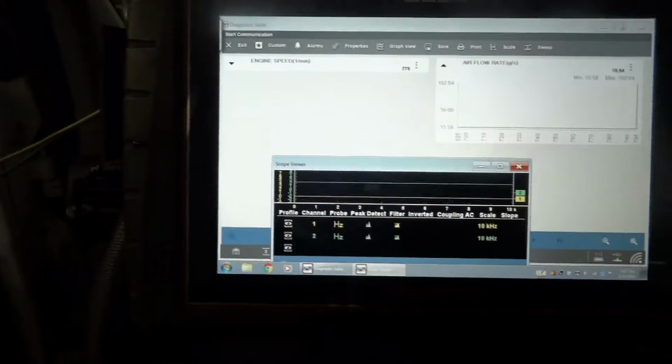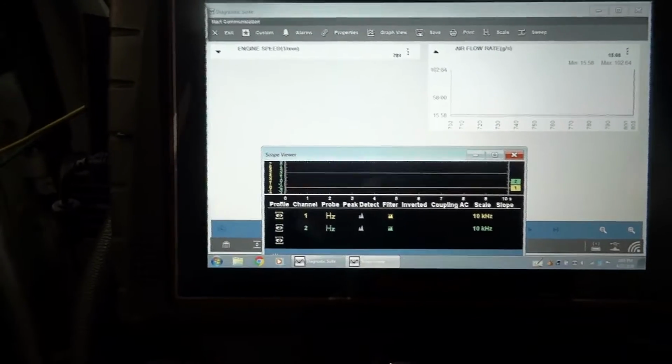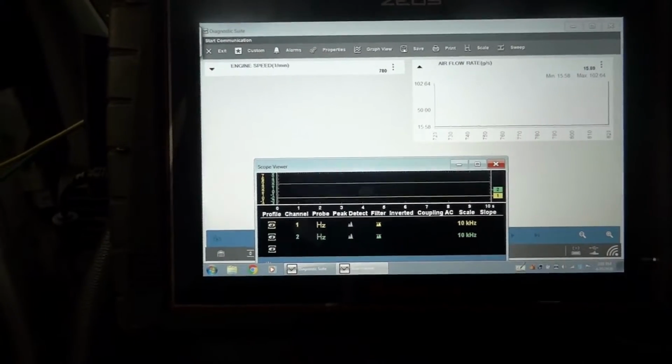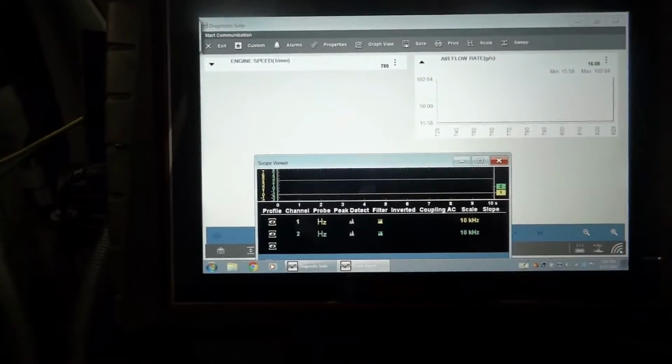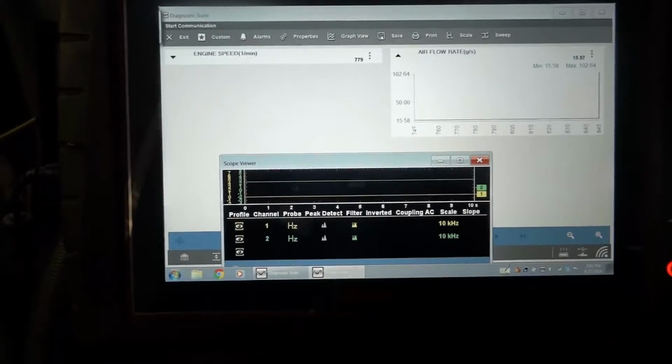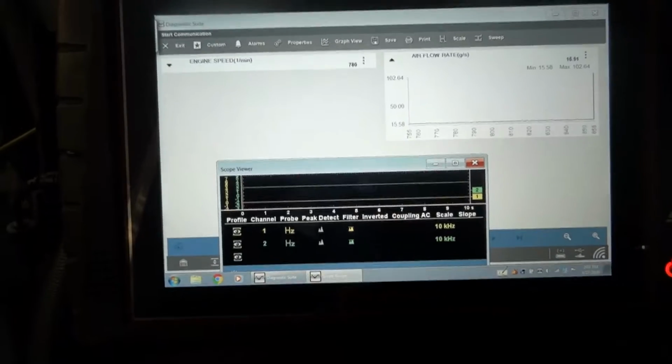I'm gonna start from the turbo, working my way up to the air cooler. We most likely have an air leak, or a gasket that's not sitting properly. So let's go under the hood and do those checks.